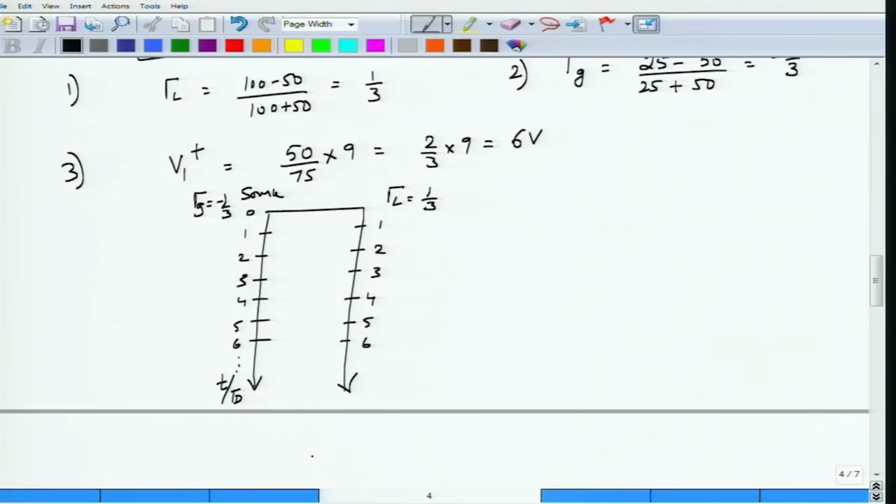Okay. Now, you begin moving the voltages. So, initially the voltage that would be launched will be 6 volts and it would propagate like this. So, this is 6 volts, and then right after this 6 volts reaches there will be reflection. So, the reflected voltage V1 minus is equal to V1 plus into gamma L, which is 6 into 1 by 3, which is 2 volts, right. So, a 2 volt is launched back. So, you can write this as 2 volt, and this is 6 volt.